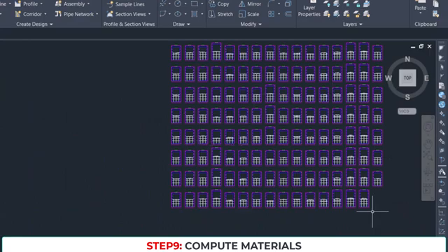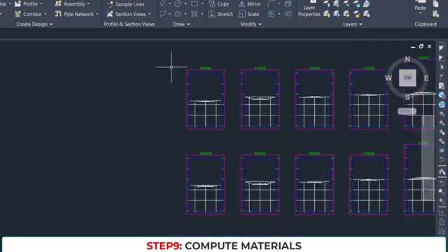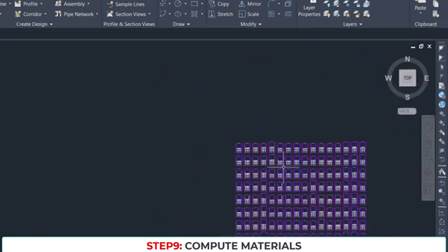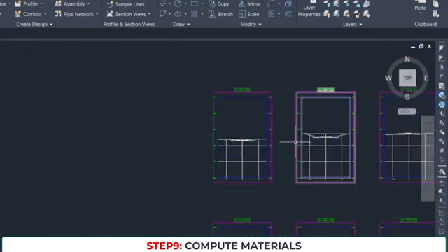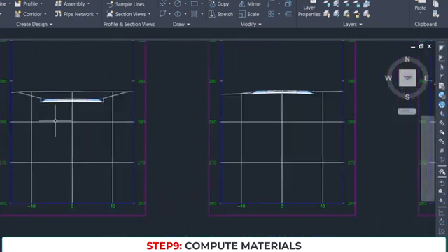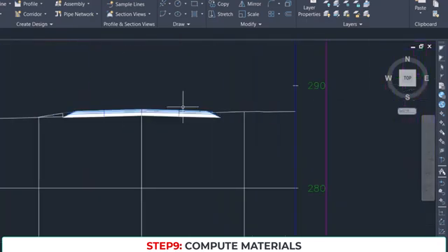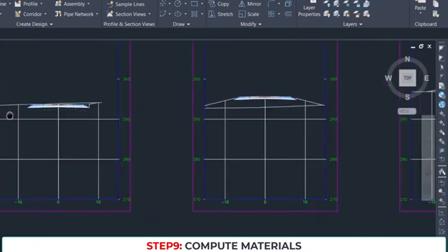That's why everything just comes in without a title block or extent. When you are using that production, it will bring up a title block and group maybe 6 of them into one sheet. Yeah, because you can see we have plenty. If you keep viewing them one after the other, you would see it's showing you the cuts, it's showing you the fill for each of them, how it's looking, and the elevations by the side.